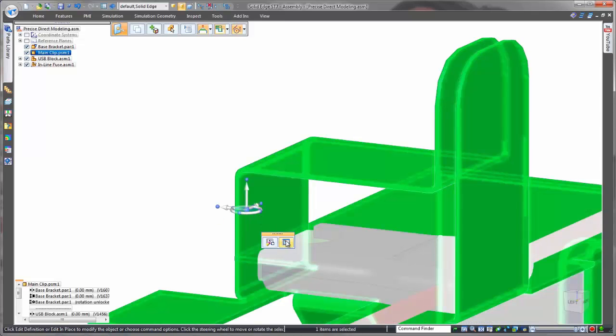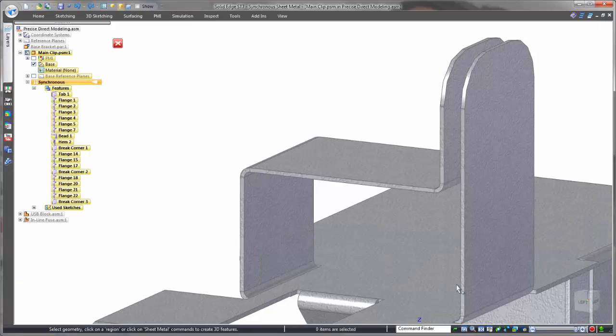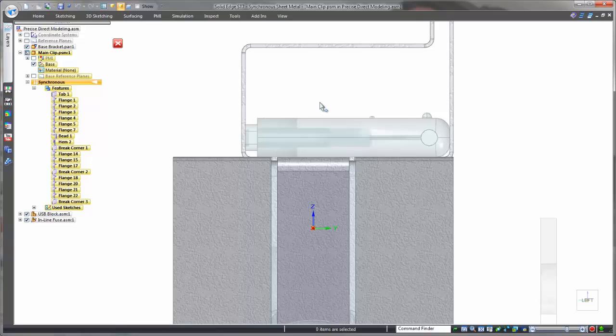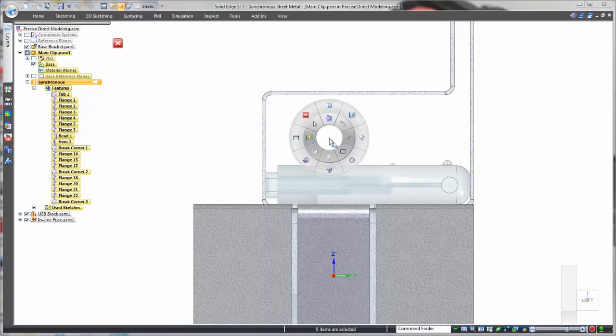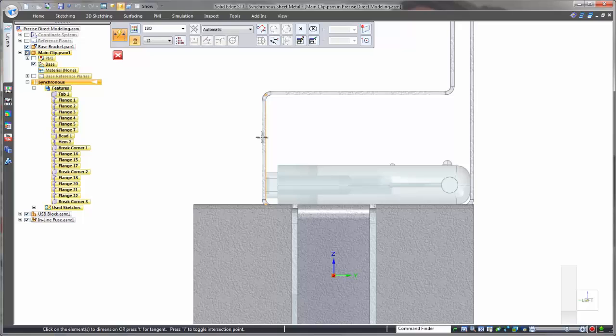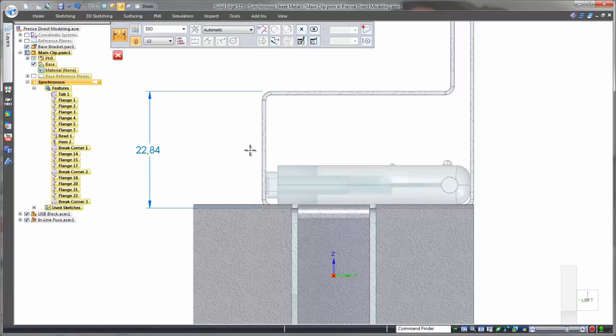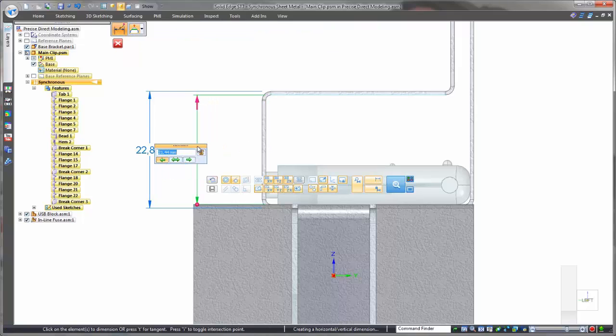For dimensional control here, we can design to the inside or outside. It doesn't matter which one we change, Solid Edge will always take into consideration the material thickness. This outside dimension, I'll just take the default value. Now let's place a dimension to the inside. This dimension I know needs a value of 9 millimeters, and if you notice the outside dimension has updated to